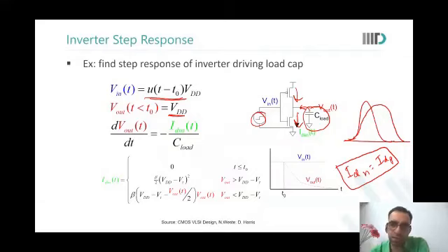Yes, sir. So the NMOS will finally sink more charge than the PMOS. So the NMOS current, either the duration or the amount, whatever we talk about, has to be more than the PMOS current. During that transition also, right? Because IDSN cannot be equal to IDSP.